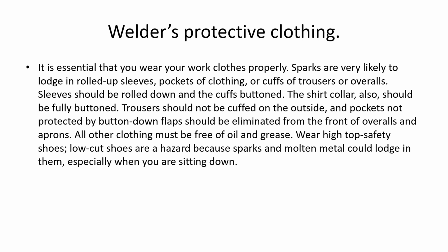Low cut shoes are a hazard because sparks and molten metal could lodge in them, especially when you're sitting down. Pretty much covers it all. You want to wear heavy clothing. You don't want cuffs on your trousers and overalls. You don't want pockets or anywhere where you're going to catch sparks. You want the sparks to hit you and bounce off and go onto the floor is what we're looking for.